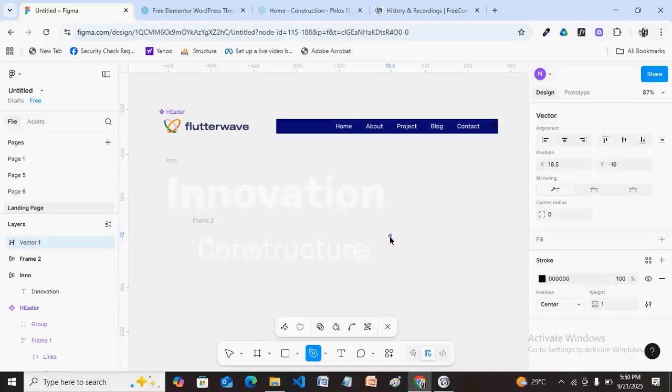You click on the particular area where you want it to start, and where you are taking that line to, also click on that side. If you just want to leave that point, press your Escape key, then close, and you can change back to the move tool, or you just hit V.